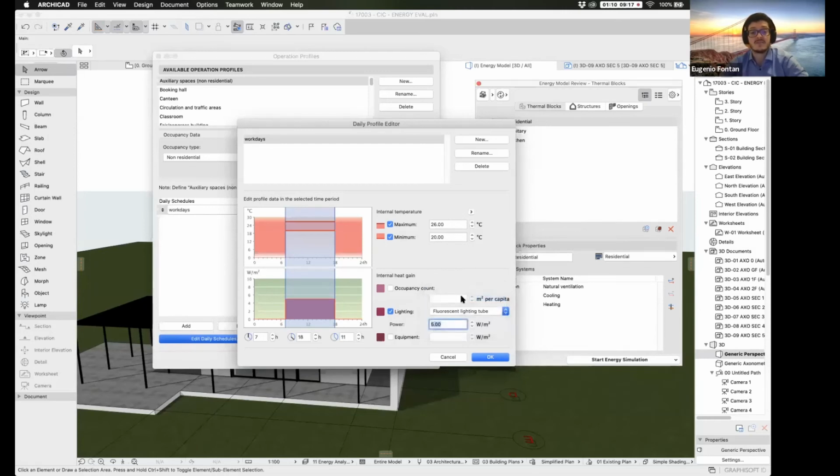These are just predefined ones, so I would put custom and input this value manually. The energy for the lighting we design needs to be calculated separately, but it shouldn't be that hard, because the power per square meter is just the total power of the lighting we're choosing divided by the square meters. That's the value we need to input here.